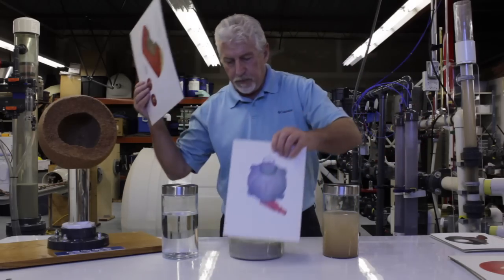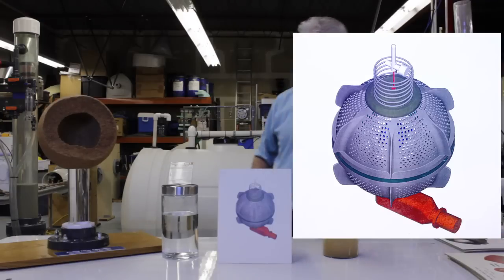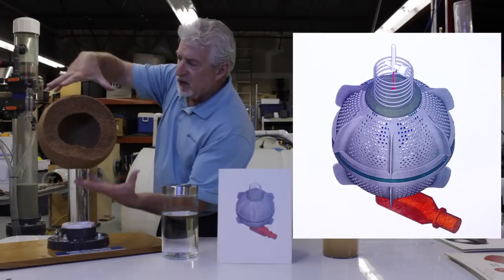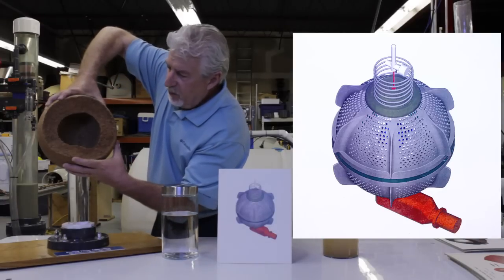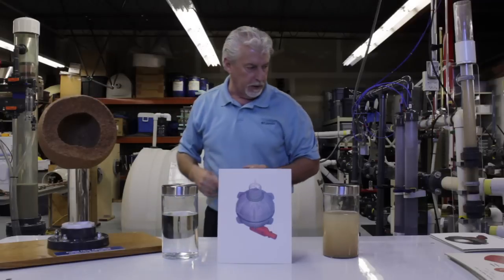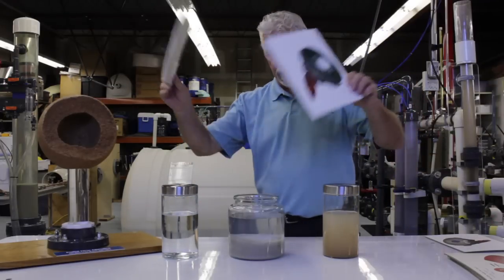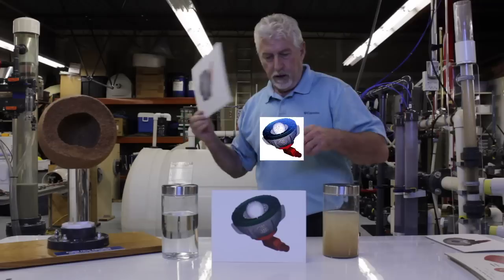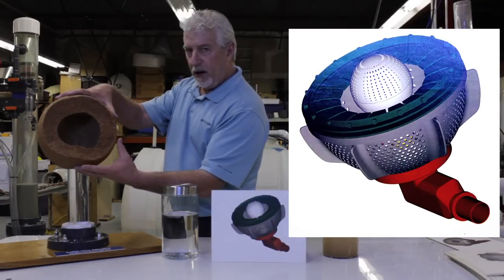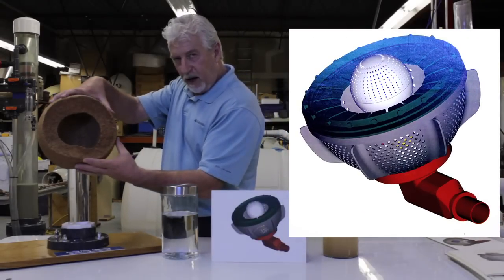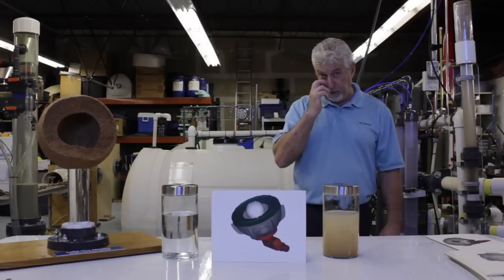Inside the tank, we have the radial flow filter. Basically 2 colander-like hemispheres perforated that are squeezing and compacting the media against the inner drain. What's the inner drain? Smaller perforated sphere inside of that one. Now we've got controlled bed depth, minimum void, everything held solid, triple surface area. Everything's wonderful. We didn't solve one problem.